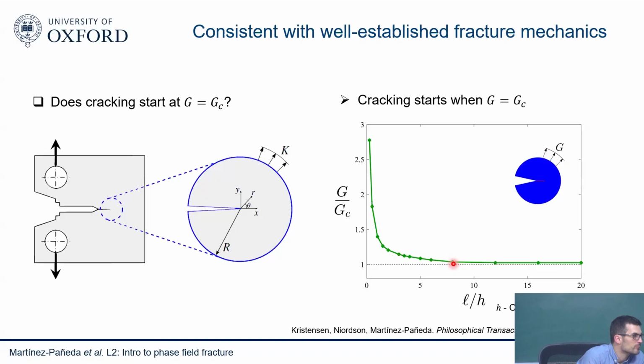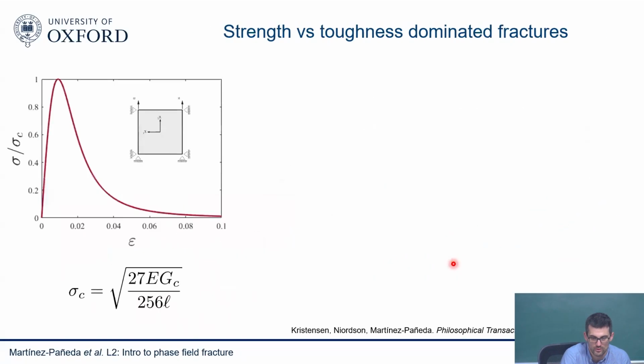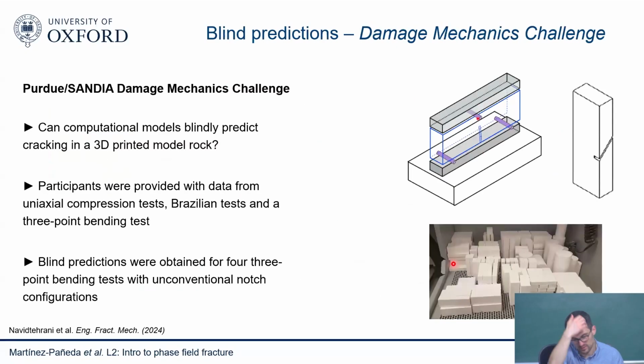Suppose the same plate we are considering in 3 dimensions, and we know it is uniform in the thickness direction. So in thickness, we can say we use fewer elements compared to where the crack is propagating. Well, you do. If you have the crack propagating through the thickness, you need to resolve that. So I'm going to show an example right now on 3D, so you'll see it. But you do need to resolve that.